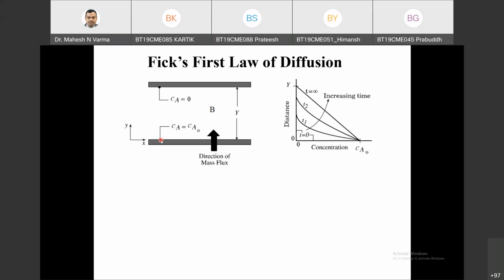You are closer actually. Equilibrium means it is assumed that the last layer of water and the first layer of air are in equilibrium. So the first layer will have a saturation concentration. That saturation concentration can be obtained by using saturated vapor pressure, psat. Total pressure divided by psat will give you the concentration here, or it is related to psat. Raoult's law is one of the limiting cases where you can obtain this.